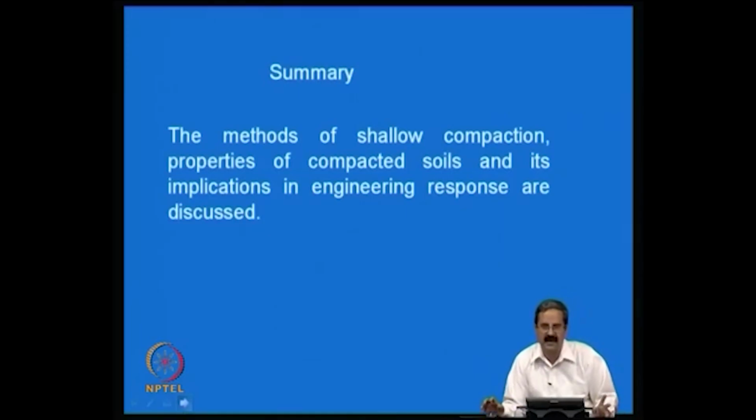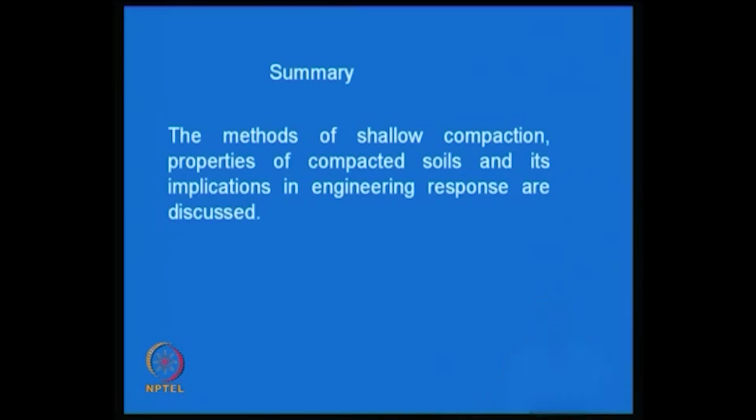There are some more points that I should mention. Normally we do a compaction test for the material passing through 19 mm, but if the material is coarser, say the lab is different and the field is different, the codes have some way of mentioning that it should be corrected, because to what extent the laboratory curve is relevant to the field depends on whether you can correct for the grain characteristics available in the field also.